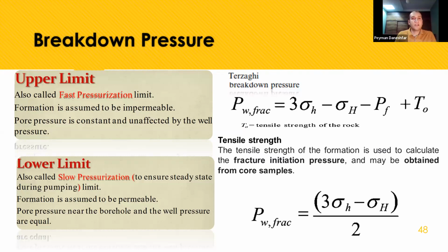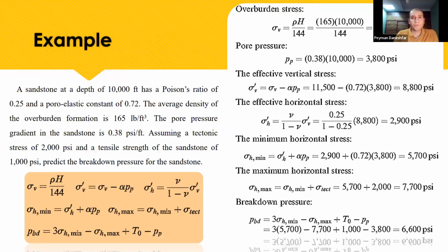And what are the tensile stresses? The tensile stress of the formation is used to calculate the fracture initiation pressure and may be obtained from core samples. Keep in mind the Terzaghi breakdown pressure.